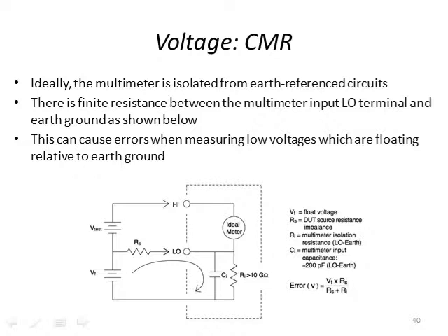So remember, when you plug your instrument in, you don't barely ground the system, so it can float. So when you're in a laboratory, it's best to have all instruments grounded with respect to an earth ground within the laboratory, so that you don't have these floating voltage configurations. However, unfortunately, most laboratories are not. So oftentimes, this can be a problem if Ri, our input impedance, is too low. Okay, then these can be more significant.